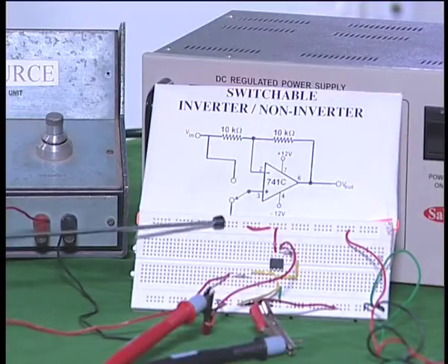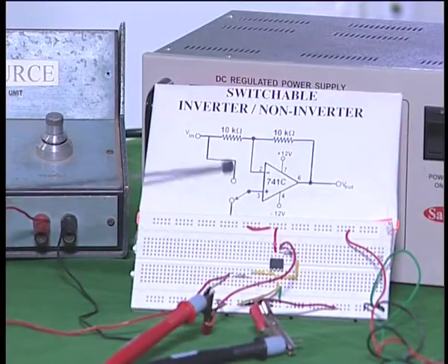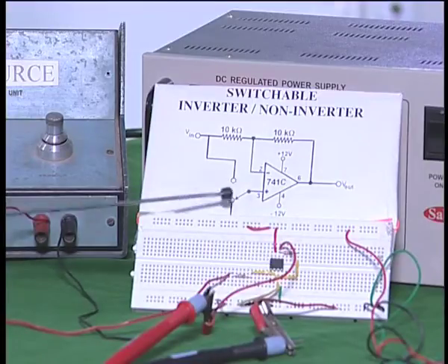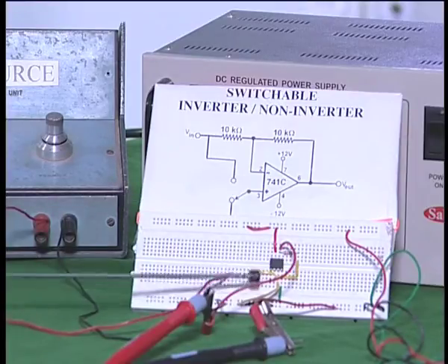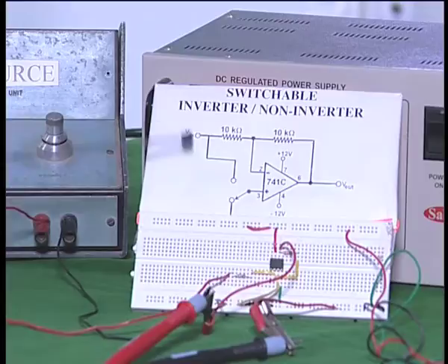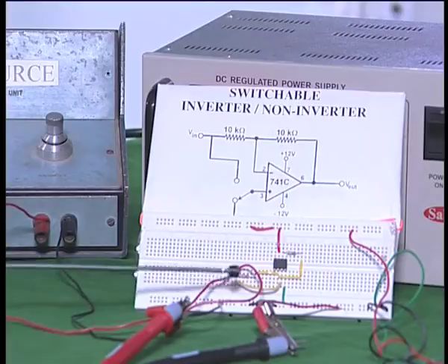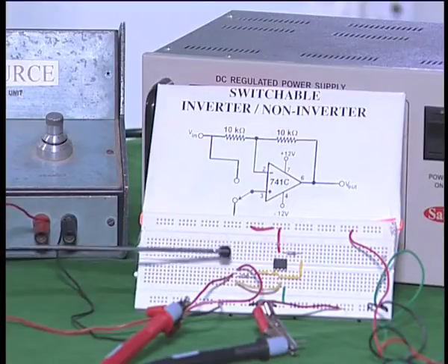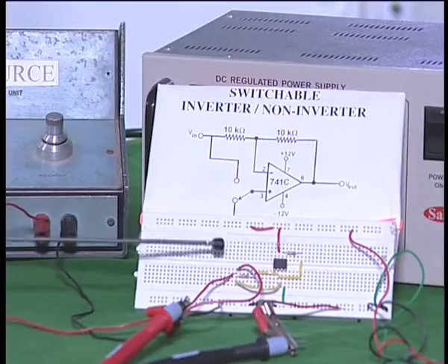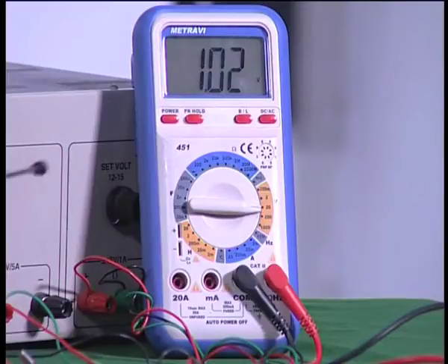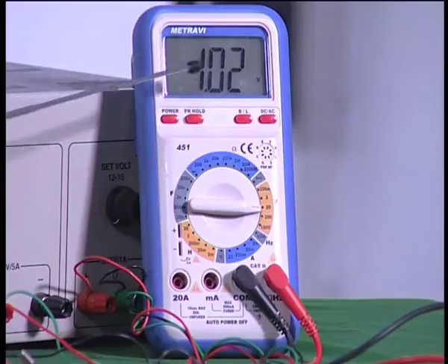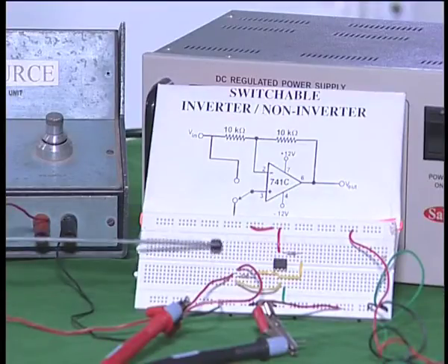What I am now going to do is remove that wire and connect it to the input. It is equivalent to having a switch and pushing it onto the other side. So, I am going to take out this yellow wire and connect it to the input, and let us now see again what is the input and what is the output. I have now switched the yellow wire from ground to the input terminal, and I am now monitoring the input voltage using the same multimeter. I want you to see the multimeter. When you look at the multimeter, you find it shows 1.02 volts, that is the input voltage, a positive voltage, because I have connected the multimeter now at the input.